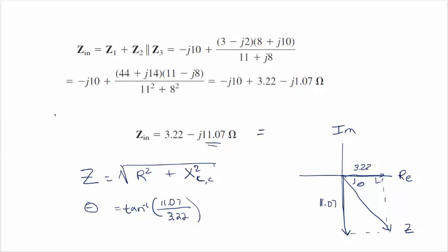The net result is this circuit is behaving like a capacitive circuit, more like an RC circuit than an RL circuit. Even though there's an inductor in it, it's not behaving inductively. The circuit at this frequency is behaving capacitively, and that will be important as we study things with varying frequencies.